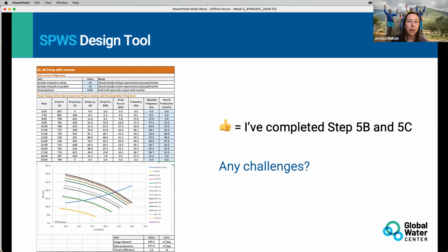You might have controllers who can do some of those adjustments. They can control the frequency if you needed to. But when we've talked about it in this course, we just mean that we're adjusting these values in our design tool to get an accurate picture of what our water production will be. So I know there's been some confusion when we say we're going to adjust the current. We're not manually adjusting the current on the pump itself. We're just adjusting our design to reflect what the pump is going to do.